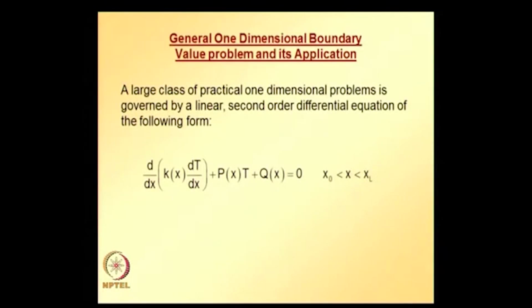A large class of practical one dimensional problems is governed by a linear second order differential equation of the following form. So for a specific problem, if you can identify the coefficients k, p and q, you can substitute them and get the equivalent element equations for that particular problem.